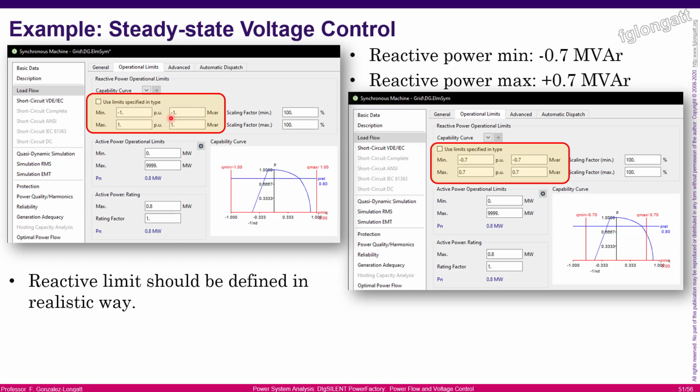than active power. What we did here is try to reduce the power production, enabling some reactive power limits, and those reactive power limits are more realistic. In this case, you can see that we are moving from 0.7 to minus 0.7. That is the limits. We are including limits for the reactive power.